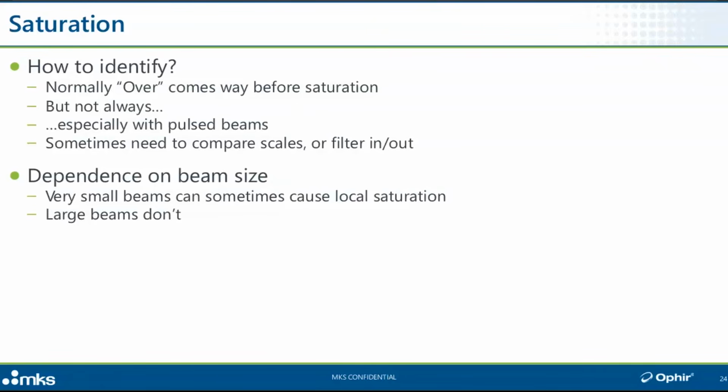So you can use that as a quick litmus test. If you see that on the 10 milliwatt scale, you were expecting to see 8 and you're seeing 6, you switch to the 100 milliwatt scale and you see 8, that's already a pretty good indication that there may be an issue and it may very likely be saturation.